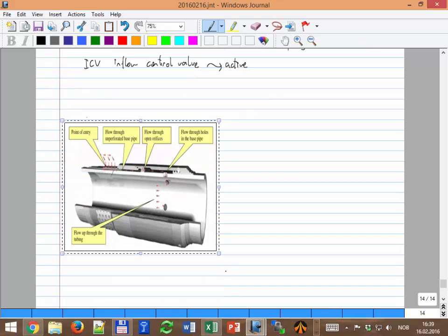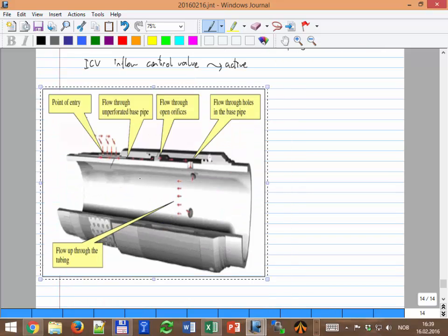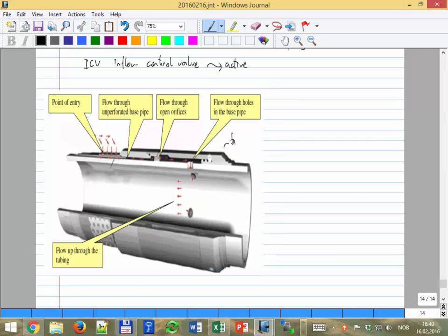Actually it's something like this. You have a mesh that impedes the sand particles from going inside the wellbore, because they will cause erosion, or maybe they accumulate in the wellbore and then restrict it. Then the flow goes through some passages that create a pressure drop, a resistance, and then you have some holes in the tubing, and here again you have flow. The formation is outside, and the flow goes all the way to the wellhead.